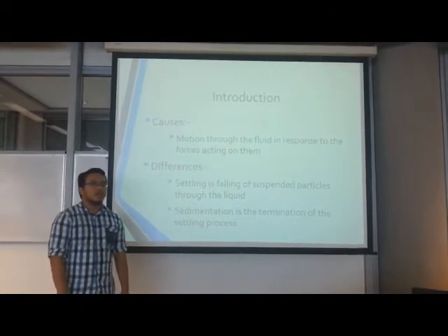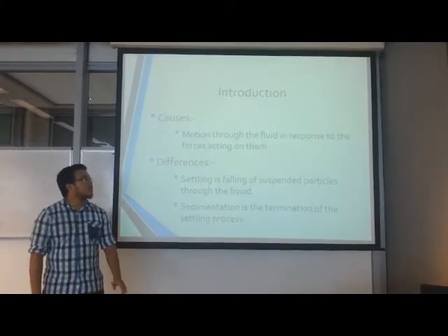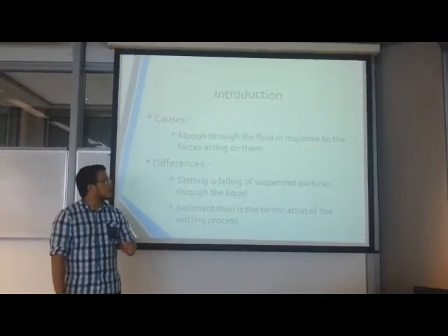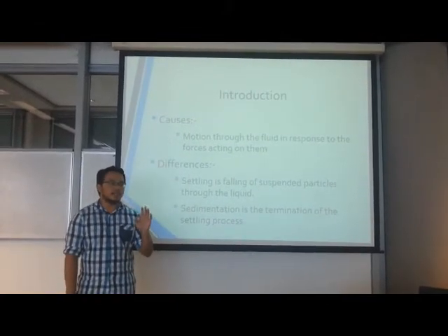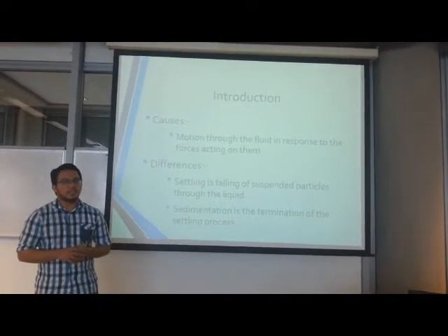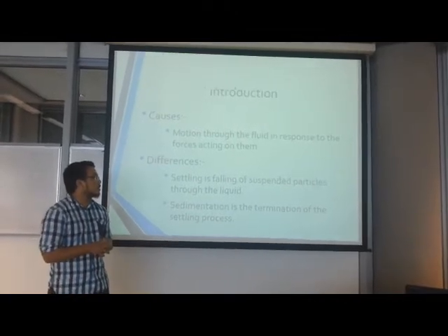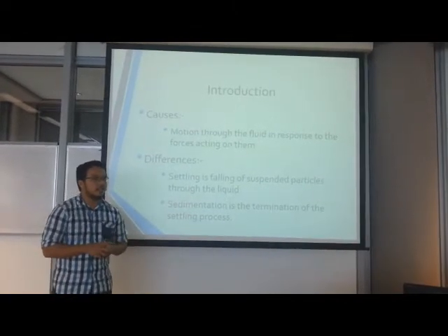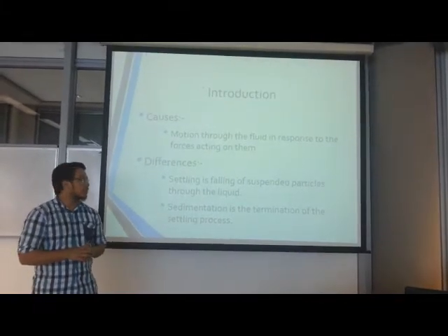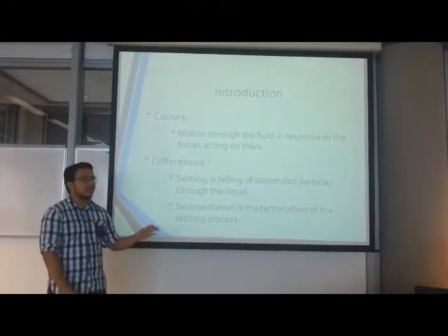So, what are the causes of sedimentation? It is caused by the motion through the fluid in response to the forces acting on them. These forces include gravity, centrifugal acceleration, and electromagnetism. The difference between settling and sedimentation is that settling is the falling of suspended particles, while sedimentation is the termination of the process of settling.